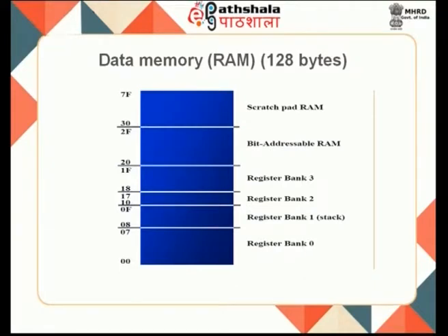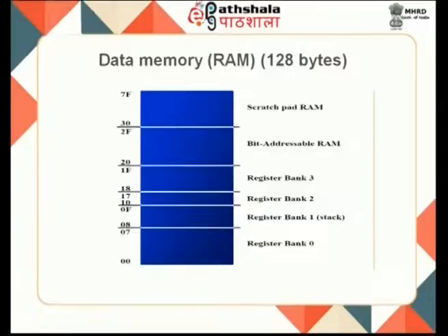So, when I am looking at my memory, this memory is very important in the 8051. As I told you, this particular memory has only 128 bytes. That means only 128 words can be stored in the random access memory of the 8051, and as I told you, from 00 to 7F I will be in a position to hold all the data. This is the address, and in that address only my data is stored, and each data is 8 bits wide.